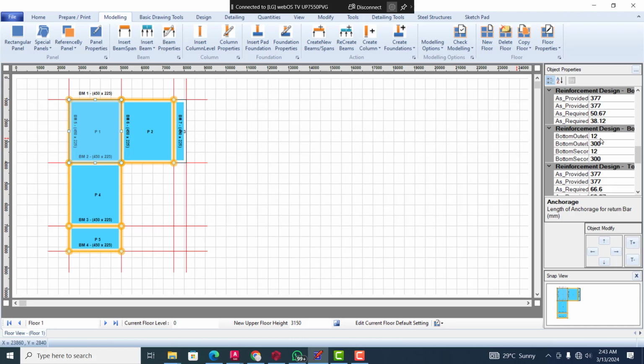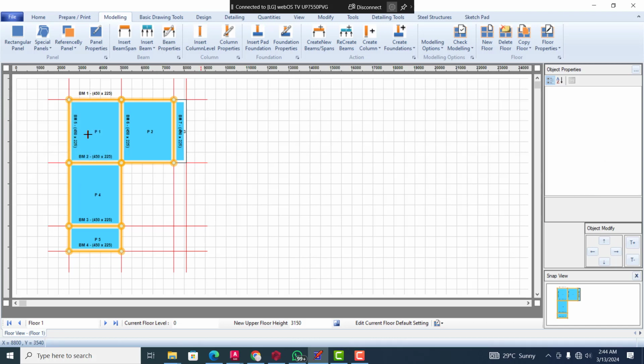So for your slab, it is mostly customary to use Y12, that's in Nigeria. Then you can do that for all the structural members as well. So for your top bar, this one is for bottom, this is for top, and then I think we have the top distribution bars. So you can do all of that, specify the reinforcement. All you need to do is just double click here and you can change the reinforcement. But we are agreeing that this reinforcement is okay, so we can leave it. When we proceed, you will see how we can correct that as well.